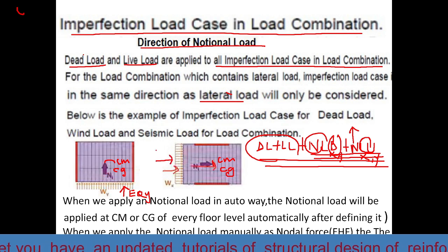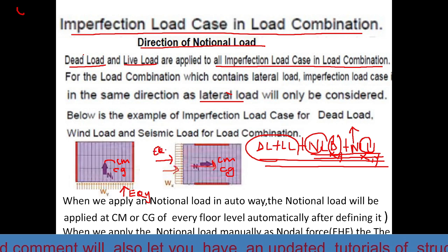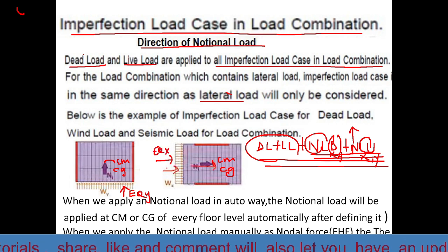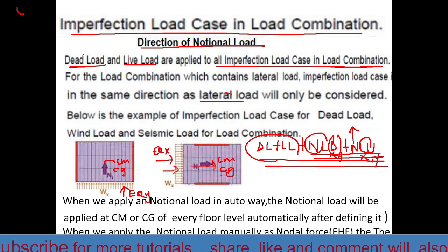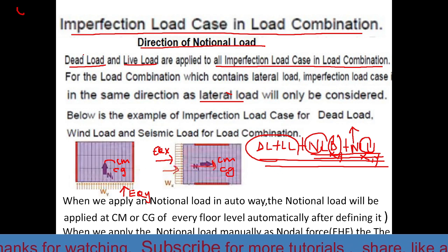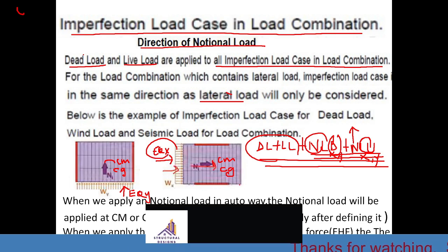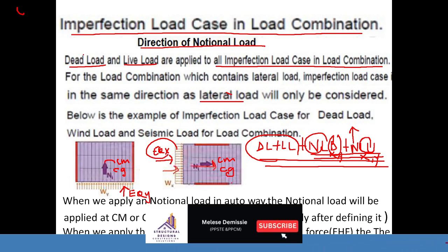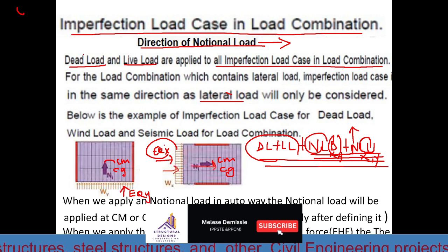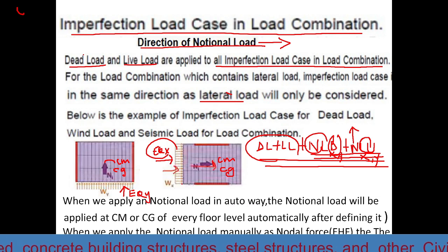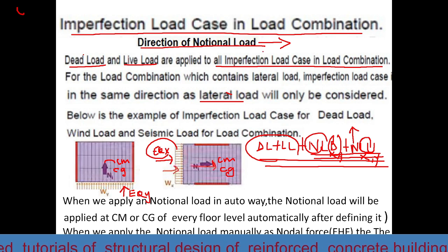And if we apply EQX in this direction, the notional load or the imperfection load will be applied along the direction of the seismic load, that means along the x direction. So the direction of the notional load has to be consistent with the direction of wind or seismic.